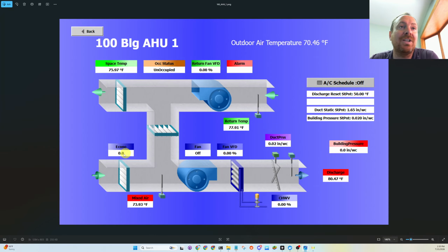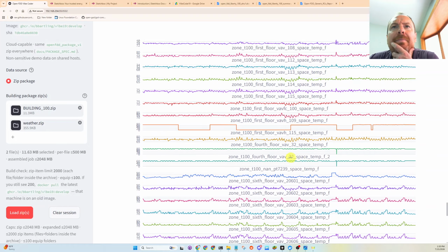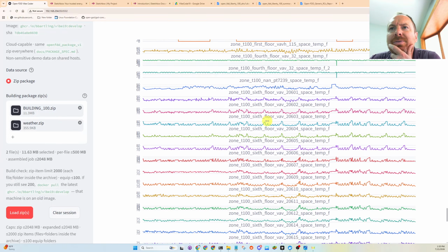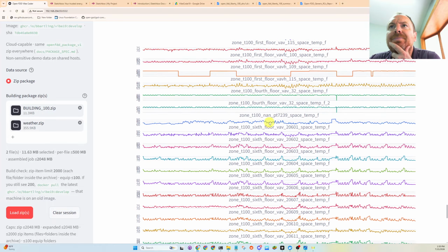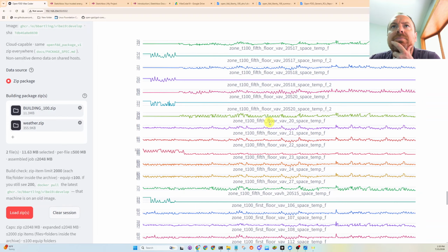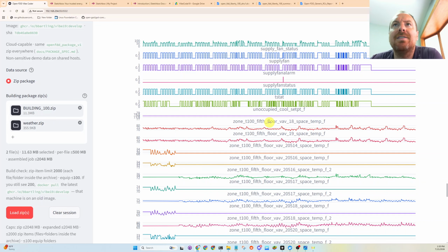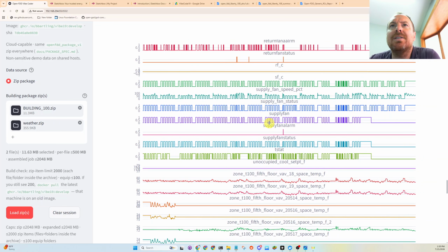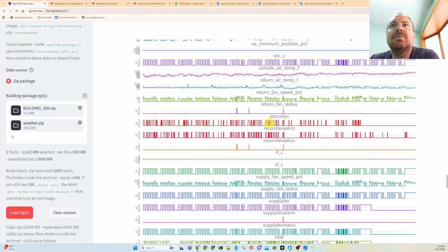So it's either 100% closed in the data or it never opens. Yeah, so many zone temps are just all over the map. A couple broken zone temperature sensors. I don't think I have enough data to get really into the weeds on individual component level.